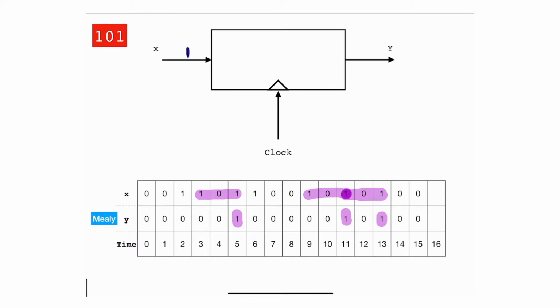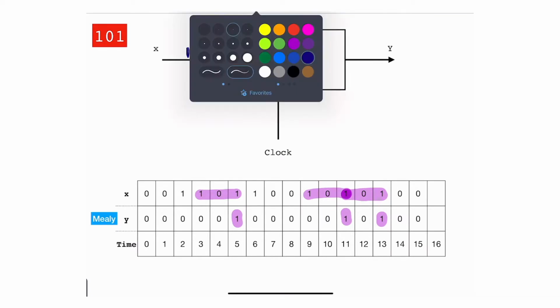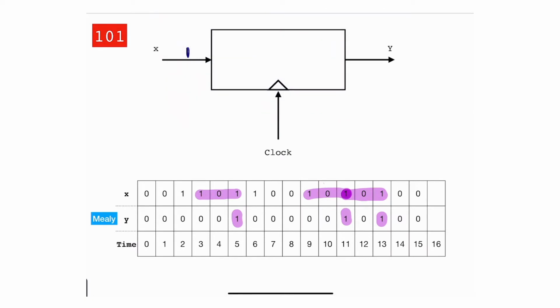If overlap is not allowed, or I decided not to allow that overlap, in other words, I don't have a moving window, but a windowed approach, meaning I will be taking a look at some window like this, and then the next window will be like this, not moving the window one unit at a time. For example, let me assume that instead of moving it one at a time, I was moving it 3 at a time, 3 at a time, 3 at a time. In that particular case, that particular output will not be asserted. But I'm making the assumption that overlap is okay.